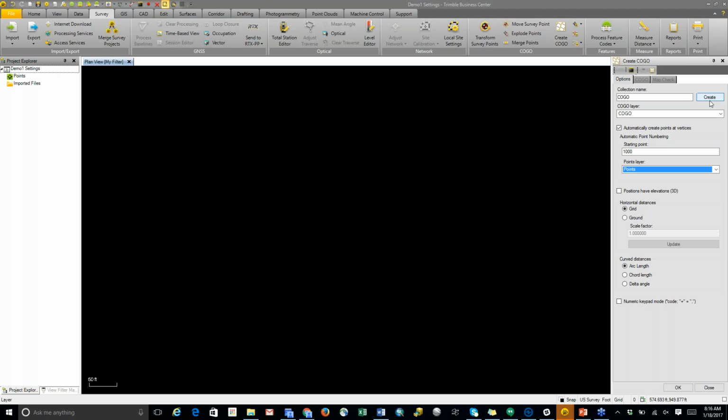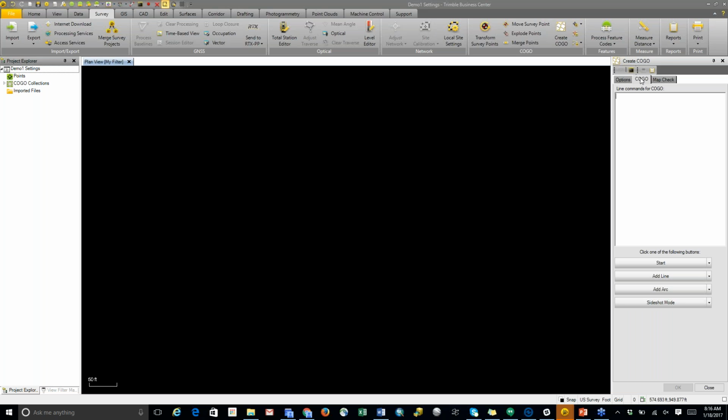So I'm going to go ahead and hit create. I've named my collection, started at point 1000. I'm going to create my collection. Once I hit the create button, I go over to the COGO tab, and you'll see here we have a nice workspace where you can start entering your text.